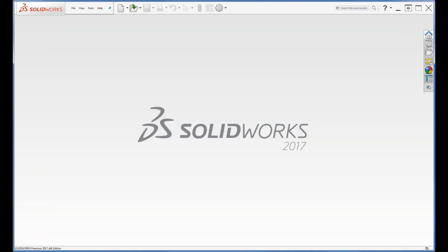Okay, so right? You can import sub-D geometry. If someone has made a sub-D model from, say, Modo or Maya or 3ds Max, we can import those directly as sub-D models. If you're just importing a scan mesh that you want to retopologize into SolidWorks geometry, then you can import that as a reference and then retopologize it. So basically, it's just the difference between importing something that's already sub-D geometry and importing something that's just a non-intelligent mesh. Okay. Does that make sense?